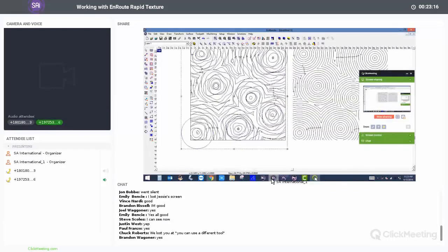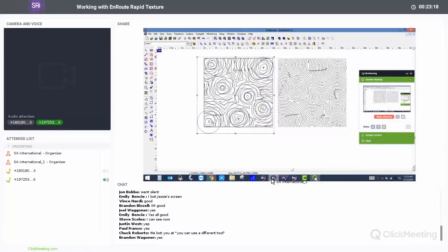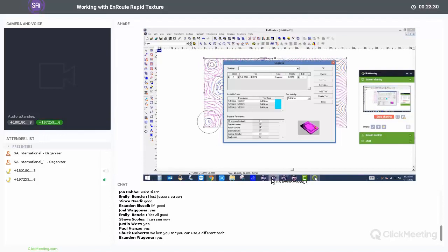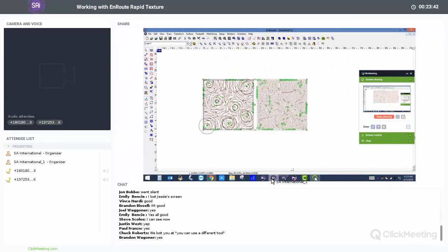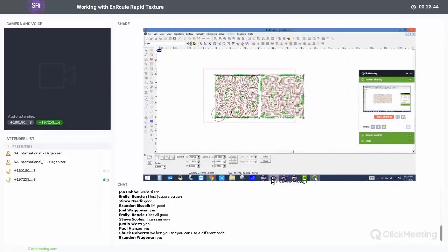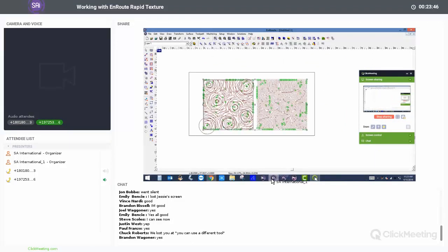Now you're going to see it's going to look more like a rose pattern or a rose bush inside here rather than symmetric circles. However, the toolpaths in them are going to be the same. And so we're just going to engrave. I'm going to go ahead and pick a conic tool for this. Our color contour is checked. And I'm going to simulate this so we can take a look at exactly what the two are going to look like.